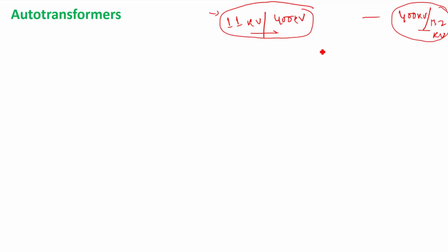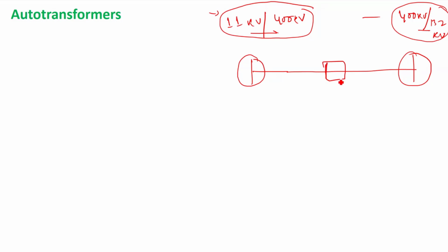And when the transformer is interconnecting, that means there is a huge transmission line between two substations. Suppose we have two substations and a lengthy transmission line, that is very long. Then in between we need some substation if there is some problem of voltage fluctuation. In order to handle that, we need an interconnecting substation, we call it ICT, interconnecting transformer substation, right?